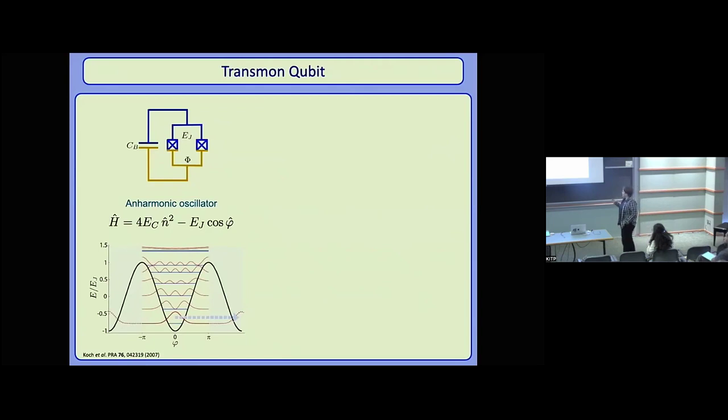The other thing that's really important is I've shown here the version of a transmon with a squid in it, and what that means is that we can tune the effective EJ by applying a flux. So this is a very frequency-tunable atom. We can tune it from probably around 1 gigahertz up to about 10 gigahertz, the ones that we're using in the device that I'll show.